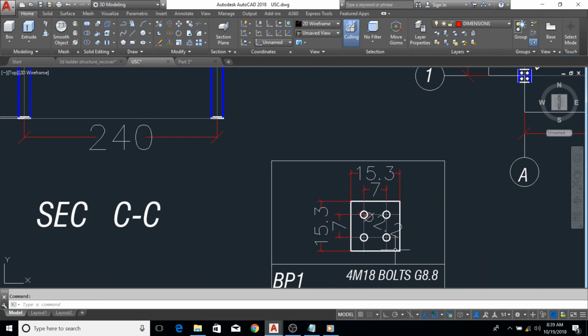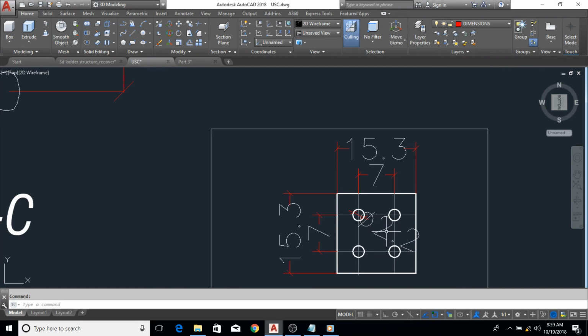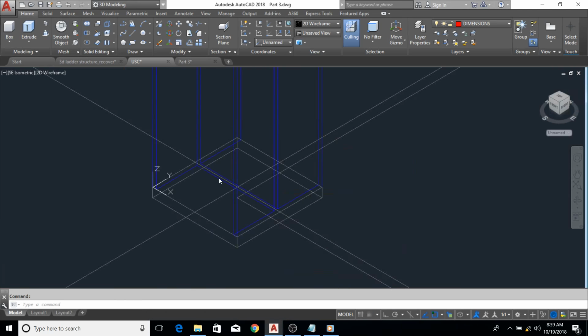So in other words, this base plate will be using 4 M18 anchor bolts for this hole. So it means that we are having a clearance of 4 mm. This is necessary to enable the leveling of the column during erection. So what I will do is come back here, then offset these lines 3.5 centimeters at each side of the line.